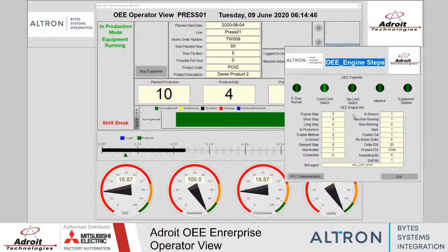with the maintenance personnel or with the operator at the machine. We can phone in, we get a phone call, and we can speak to the operator and say, listen, what is going on? Look for me. Is it in production? Okay, yeah, it is. Is the machine running? Yes, it's running. Is the equipment on top interlocked? No, it's not interlocked. Is it green or red? Yes, it's green, so it's not interlocked. So we haven't got that problem, and we can do fault finding that way.